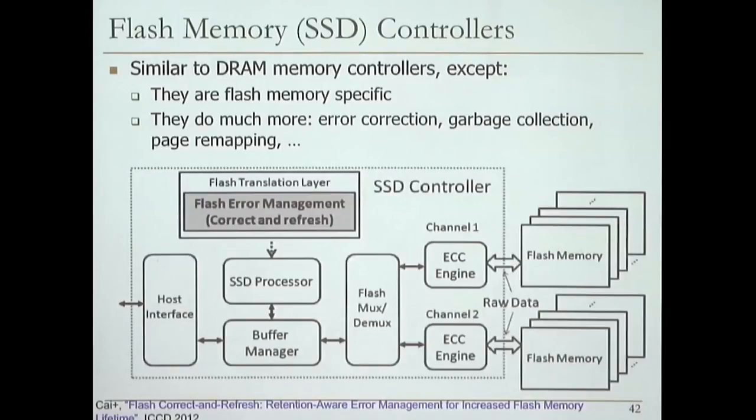And you need to have a DRAM controller inside a flash controller to make this work, because you have that DRAM to improve the performance of writes, for example. You can write it to DRAM. It's used for many things, actually. But one of the major things is to do the mapping of the logical pages to physical pages. So a flash controller actually does a lot of mapping of the data to ensure that long latencies are not experienced by the system.